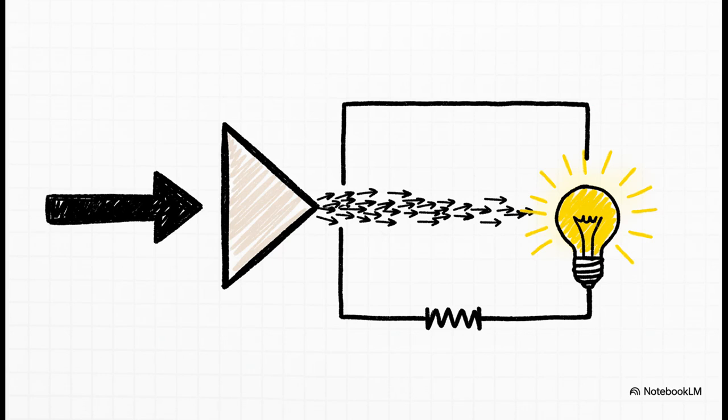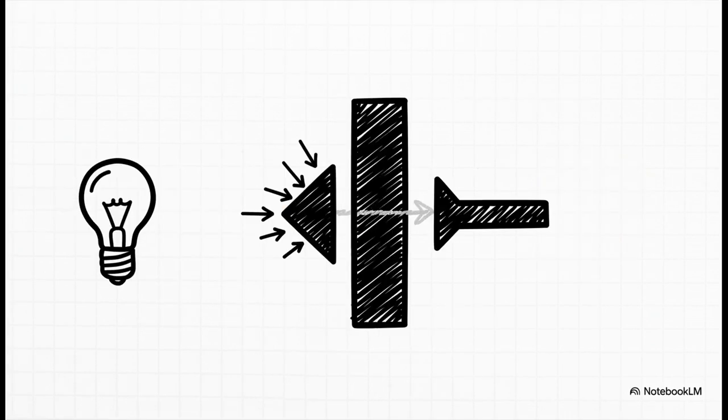This is when the diode is on. What's happening here? Well, we're applying a positive voltage from the anode to the cathode, and that one-way gate just swings wide open. We do need to overcome a tiny little turn-on voltage, but once we do, current just flows freely. And as you can see from the curve, it doesn't just increase, it increases exponentially.